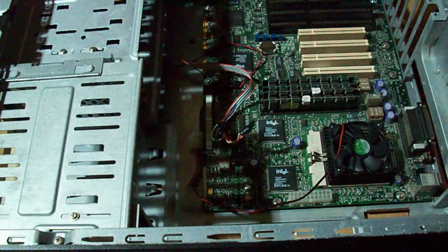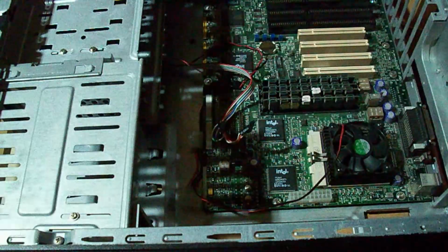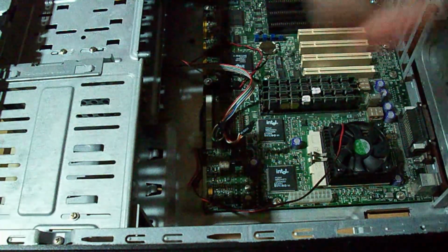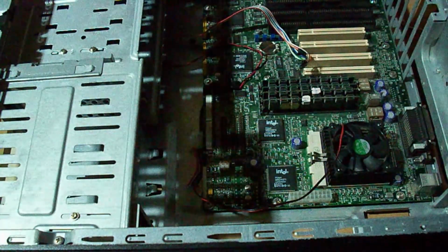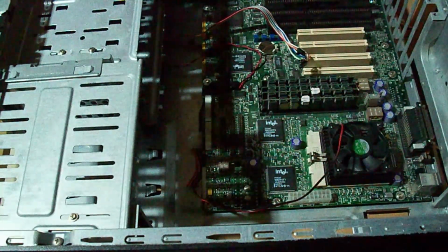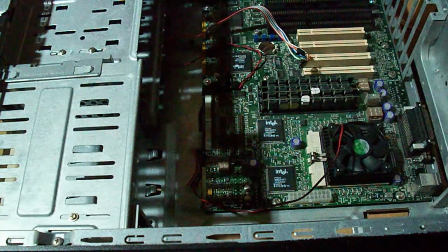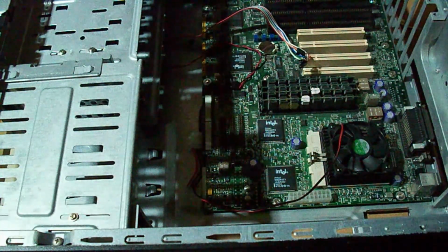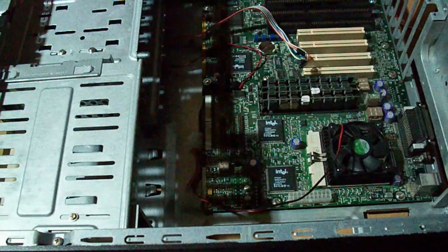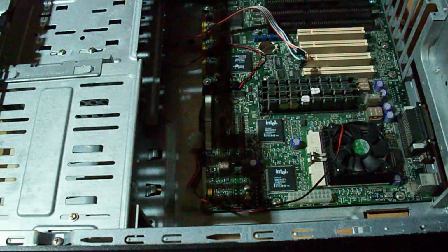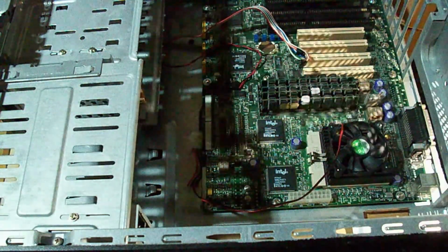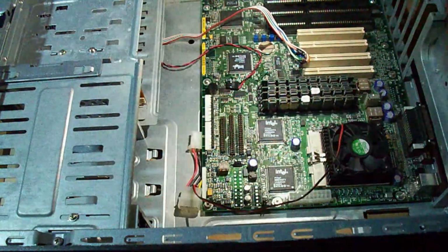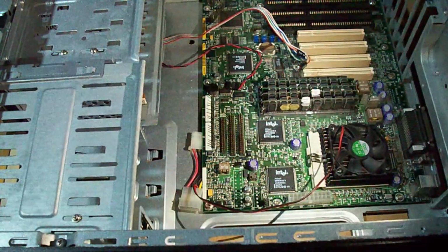Although it is not absolutely necessary, it is advisable to install all the supports and all the screws that the board has holes for, because if you don't do that, it is quite easy to bend the board when installing the rest of the components, like the cords or the cables, and you can easily damage the board if you flex it too much.